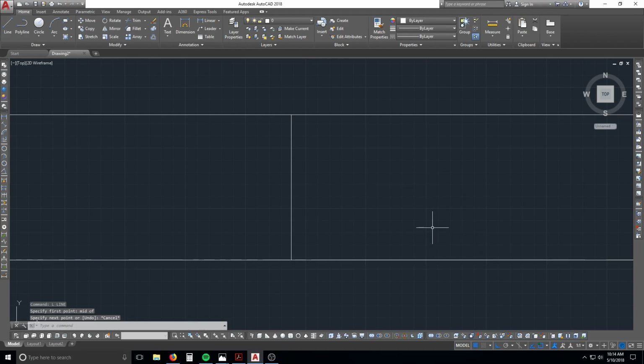And that was a left click to get that to do that, by the way. So if you're in the middle of drawing a line and you want to make sure it's exactly on the midpoint or the endpoint or the tangent, and it's not showing up, or if it's a node, which is kind of like just a speck or a point on a line that you've identified, you can type in those.